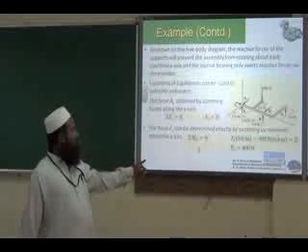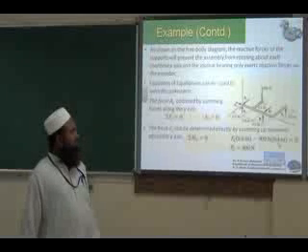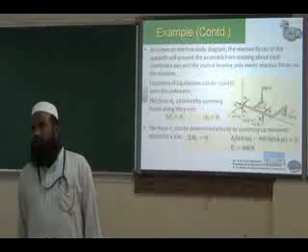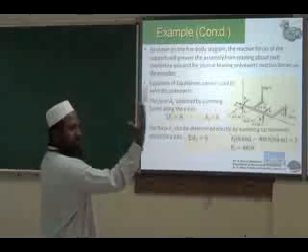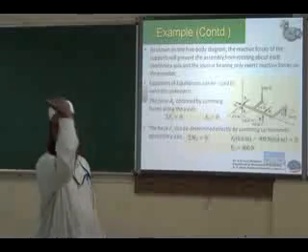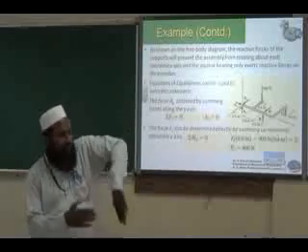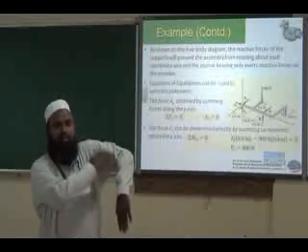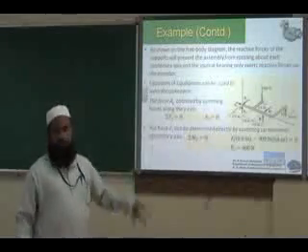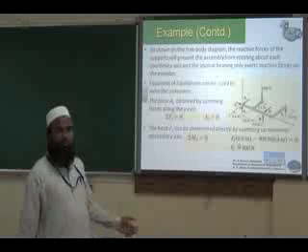So if you write that moment equation, sigma My equals 0: Fc times 0.6 minus 900 times 0.4, because we consider anti-clockwise as positive and clockwise as negative. Fc is acting in this direction, this is the moment arm, so it makes rotation in anti-clockwise direction, positive. Whereas the 900 Newton force is acting like this, its moment arm is here, so it will make rotation in clockwise direction, negative. So Fc's moment is positive, whereas 900's moment will be negative. So we finally got Fc as 600 Newton.